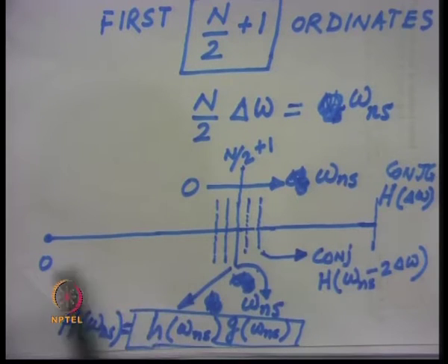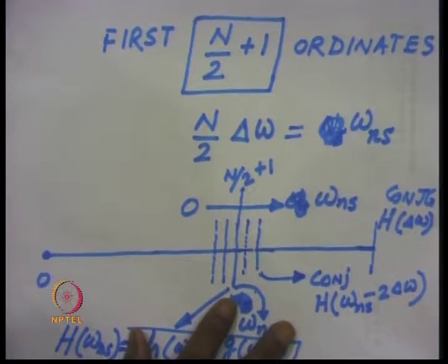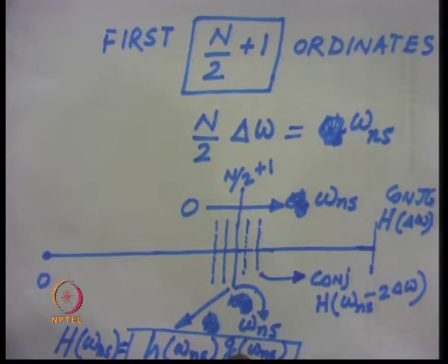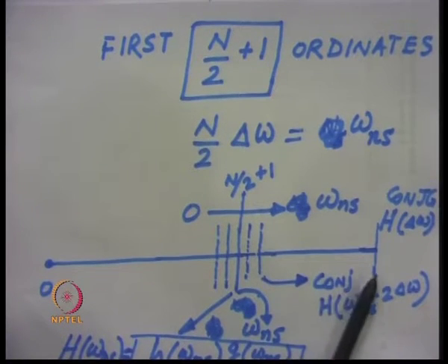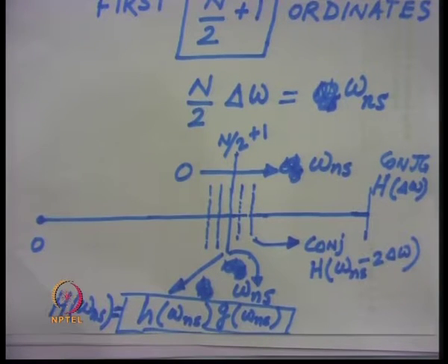So, in that fashion, if we take 32 sampled values of the ground motion, then we will get 32 small h omega values and capital H omega values. This capital H omega value is nothing but the small h omega value multiplied by the frequency contents of the ground motion, and this multiplication is a quantity which is a complex number.